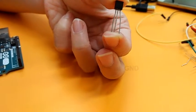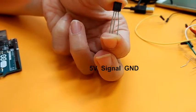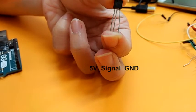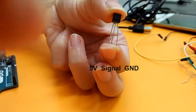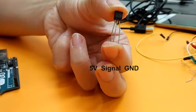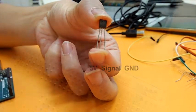The emphasis of the polarity for the temperature sensor is very high, because if we connect the sensor the opposite way, the sensor will heat up to over 200 degrees Celsius and you will get hurt if you touch it. So always make sure that the flat side is facing you while you are connecting the circuit.